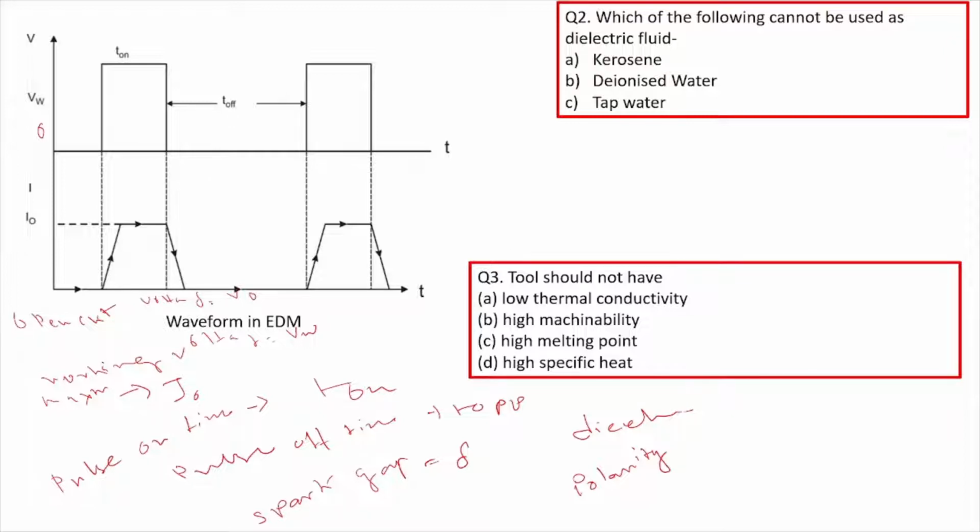So that's why, we have seen that the dielectric fluid should provide an oxygen-free machining environment. So here there is huge importance of that dielectric fluid itself. Generally kerosene and deionized water, we have seen, are used as dielectric fluid in EDM, but tap water